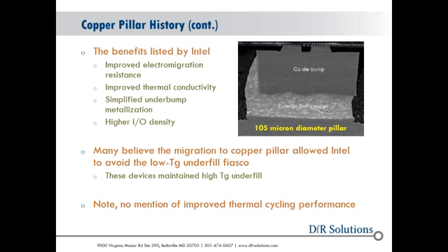So TG is glass transition temperature. It's the temperature at which the epoxy underfill goes from being relatively rigid and stiff to a very soft, rubbery kind of material. There are a lot of companies that, because of the weakness of the ELK or ULK layer that we talked about, have problems with bump cracking, which again we'll talk about in a little more detail.